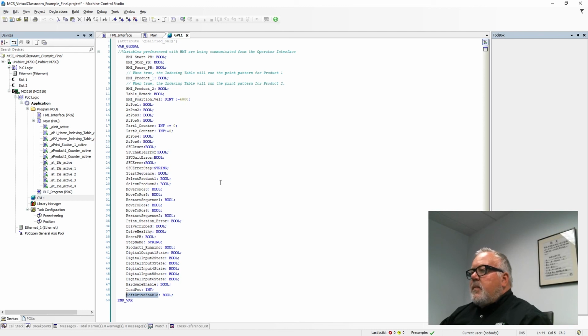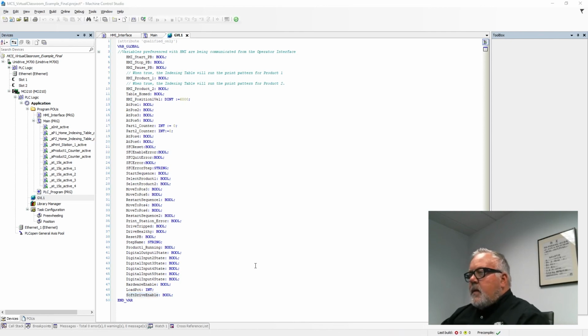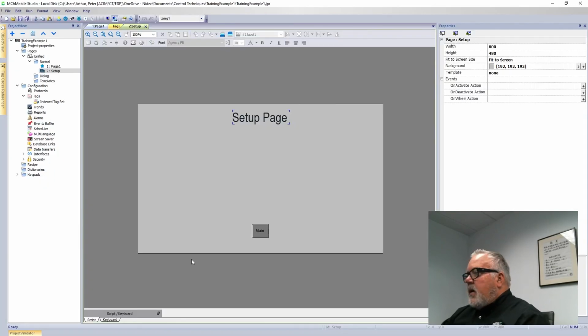And that's why you said at the beginning that the tags as you define them in Machine Control Studio are both pointing to the same parameter in menu 18. Yep. So basically, they are both writing to that parameter. Correct. And I understand why, because this HMI, even though it's made by XR, is third party. It's not related to Control Techniques. It's exactly third party, yeah.